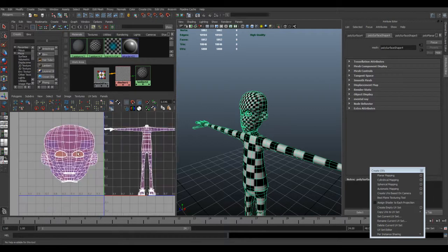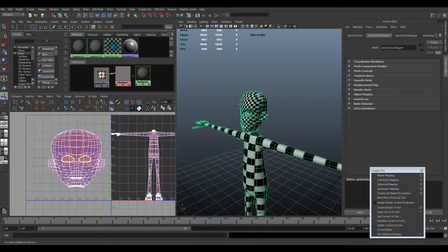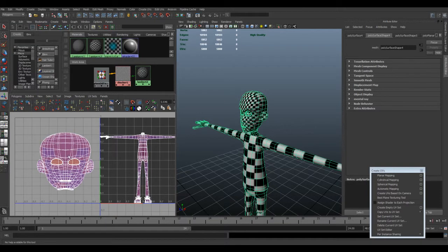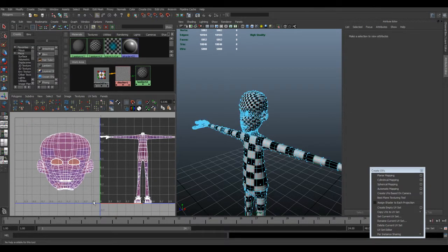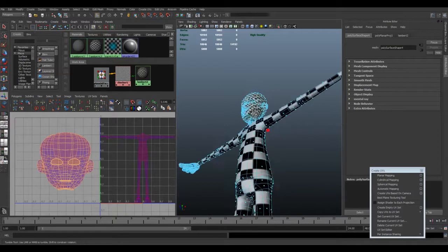Okay, so now I'm going to start cutting his head up a little bit. What I'd like to do is stretch it out, if you imagine like Hannibal Lecter, if I was Hannibal Lecter and I was going to cut the back of his head and start stretching it out. Now, rather than using a planar projection like I've just used, I want to grab these faces. I grab them in here to make it a bit easier for myself.